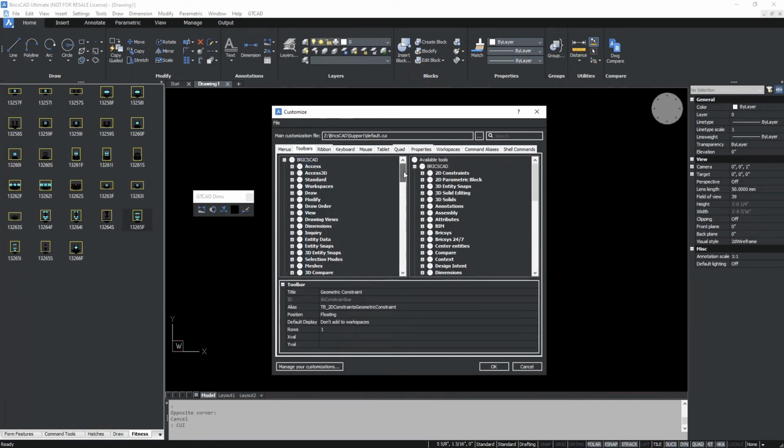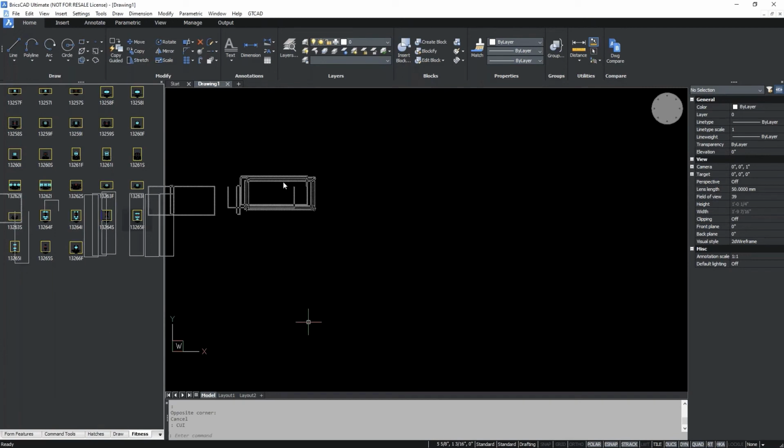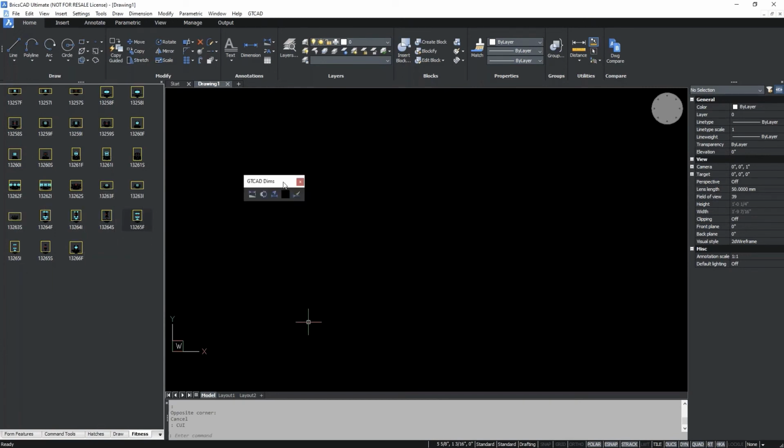If you can use the AutoCAD CUI editor, you can use this straight away. So I will say OK. And the worst thing that may happen, and it did happen, is that your toolbars can sometimes go over onto screen 1 because I like to use screen 2, my big monitor, for CAD. So I had to scoot it back over. But that's it. That's what's involved with migrating things over from CUIs.